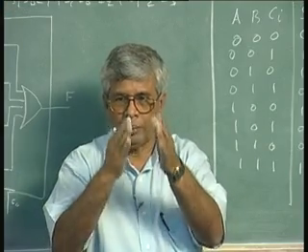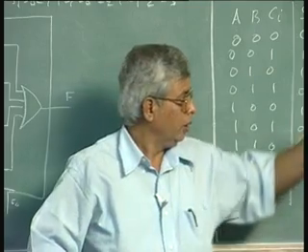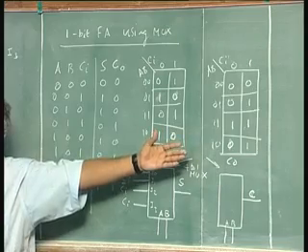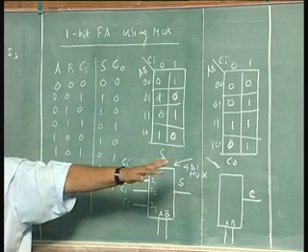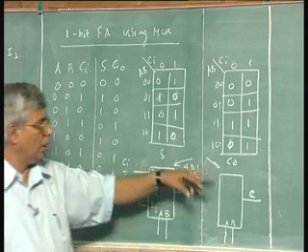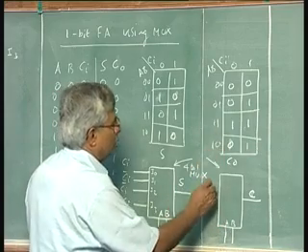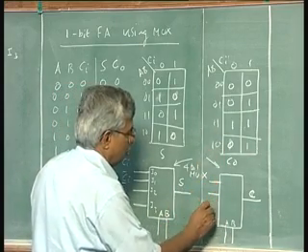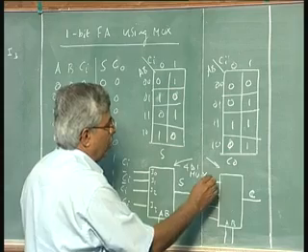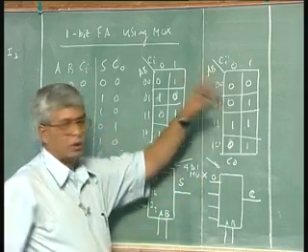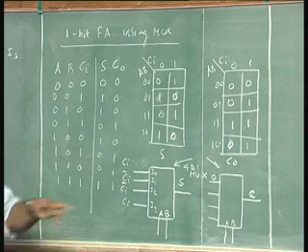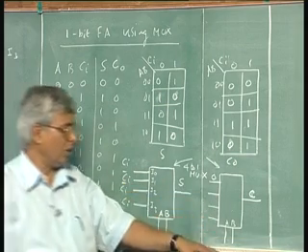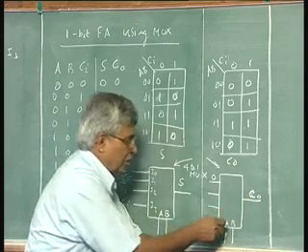On a given 4 to 1 mux, the given Karnaugh map to get the function implemented. Now, when AB is 0 0, output is 0, there is no carry irrespective of whether Ci is 0 or Ci is 1. So, I put a 0 here, carry is always 0 if AB is 0 0.